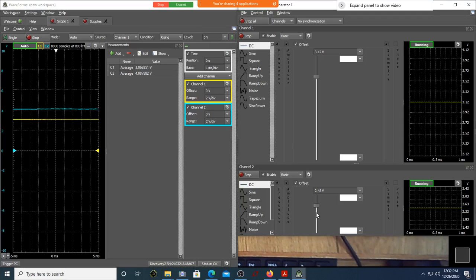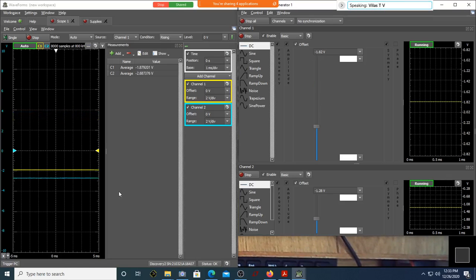Now if I keep it somewhere here, how do you get minus V sat? V plus lesser than this. I said V plus is this, V minus is that. V plus should be less than V minus so that you get minus V sat. Please don't try to keep both of them the same. Don't ask what happens if both are the same, because even the smallest noise will make it go to the other level. Correct? Because we are looking at whether it is more than or less than.